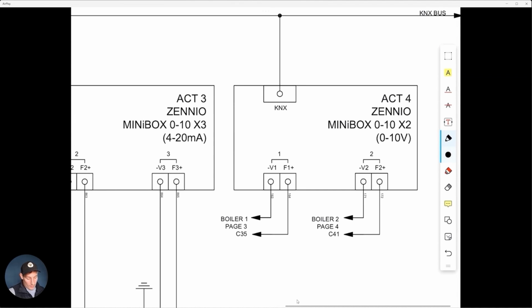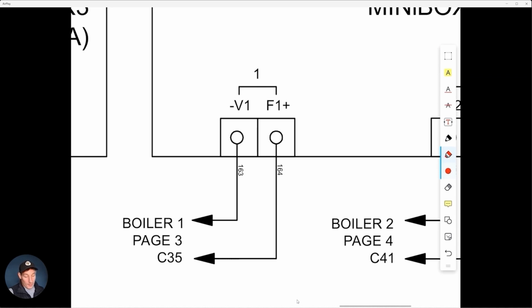Okay. So now on page 11, D117, let's have a look at what those cables are doing and where they're connected. And you'll also see, if you look closely, these cable identification numbers are the same on this page as they are on the other page, just to show that we're using the same cable here. If they were different cables, they'd be identified differently.